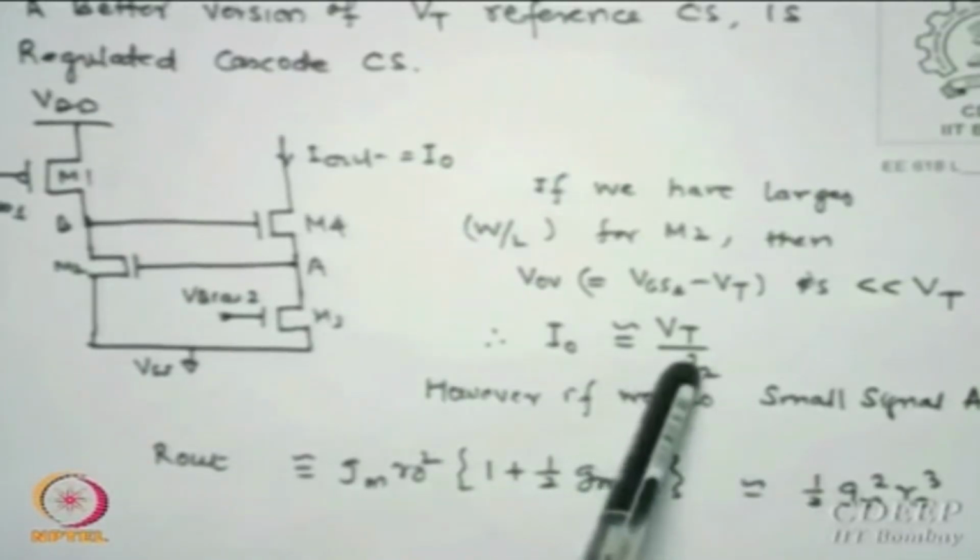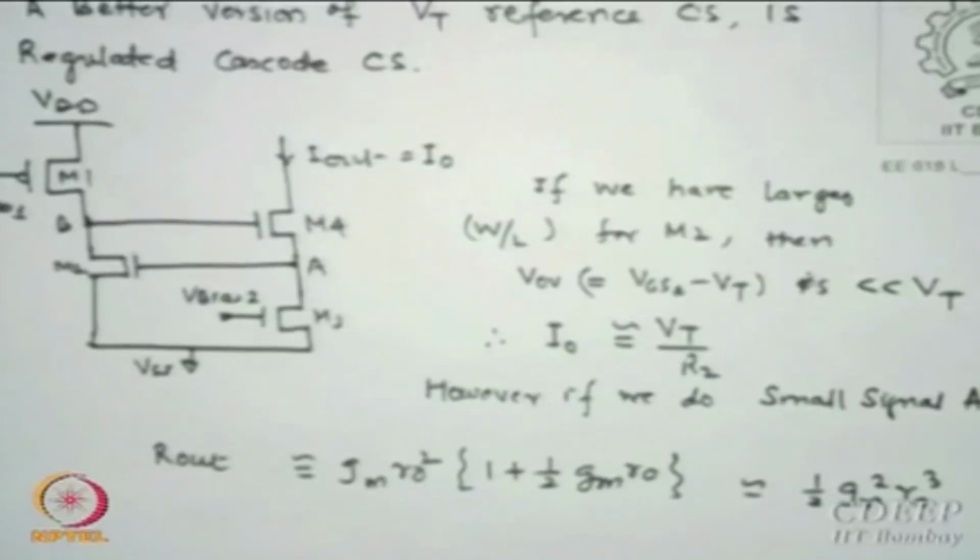And this is of opposite polarity, because please remember one interesting feature. Resistances normally, if you have learnt earlier, have a positive temperature coefficient, that is resistance increases with temperature, but all semiconductor resistors have negative temperature coefficients. Mu is proportional to T to the power minus 3/2. Is that clear?